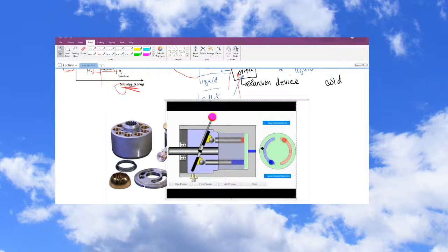And so this here shows the inlet and outlet, which is basically your valves and your camshaft. So the shape of this port would be like a camshaft. If I had a big fat opening and then it goes skinny for some weird reason, that'd be like having a fast opening camshaft. You come across this port and all of a sudden, boom, it fills with air really fast. Or if I had it fat in the middle, it'd be like having a lot of lift on a cam. So this shape kind of simulates a camshaft profile.